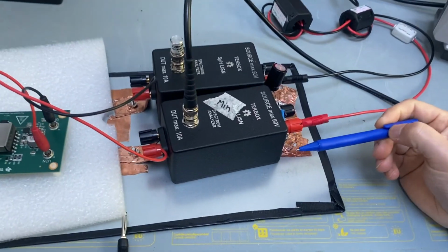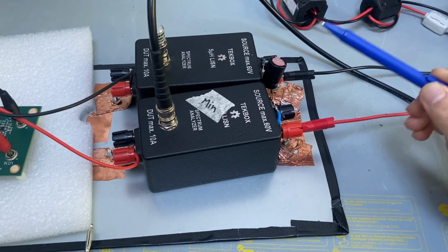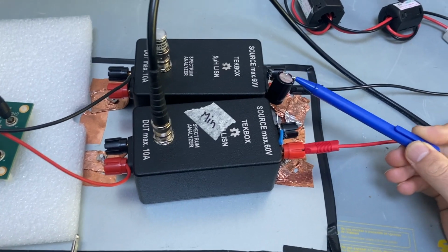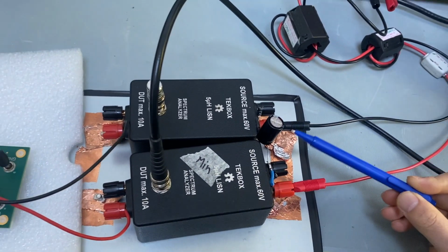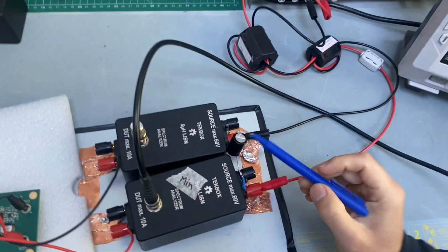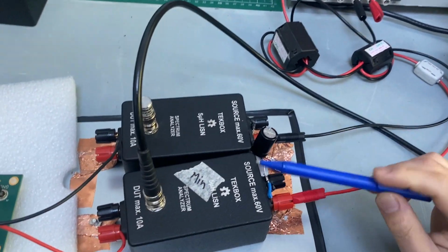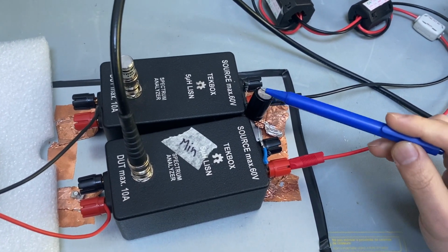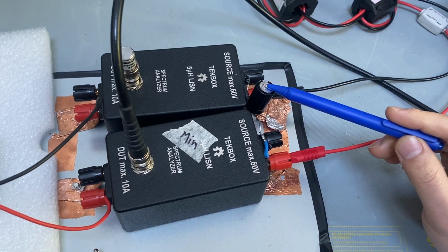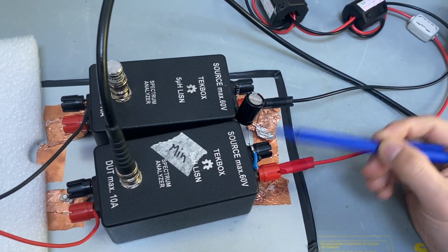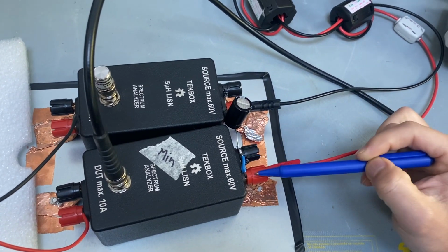Okay, so let's start. As you can see here, this is a typical CISPR 25 LISN setup. You will probably notice you have a big capacitor. If we look at the capacitance value of this big electrolytic cap, it is 1000 microfarad. Obviously, the LISNs are rated at 60 volts, so this electrolytic cap doesn't need to be very high voltage rated. You will also notice there are two small caps here and here across the LISN terminals.